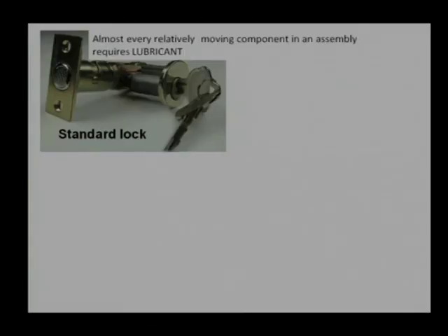I want to give more emphasis on the reduction in wear rate compared to reduction in friction, as was pointed out in the earlier lecture. Wear reduction is much more compared to friction reduction. Friction reduction can be 100 times, but wear reduction can be 10,000 times using a proper lubrication mechanism. It is really very interesting, and we have a number of applications where lubrication is required.